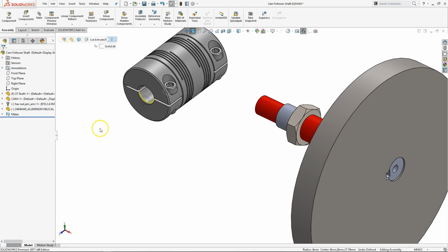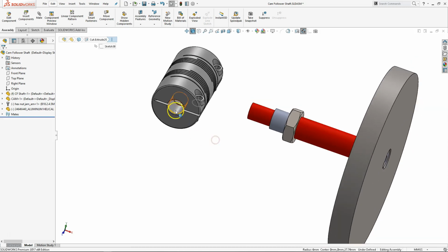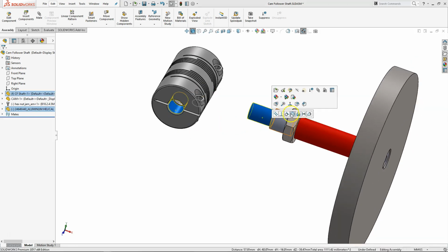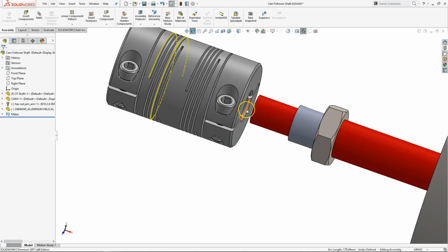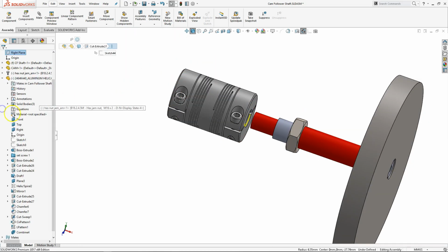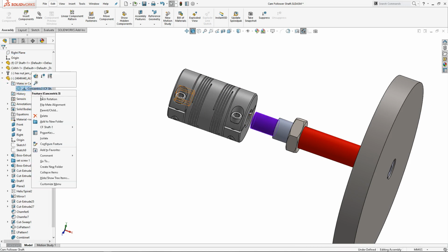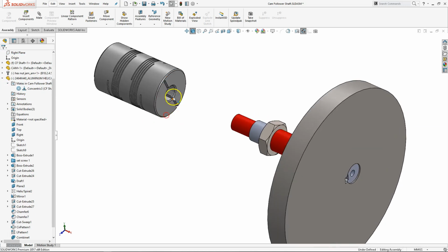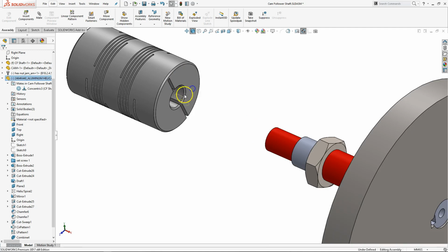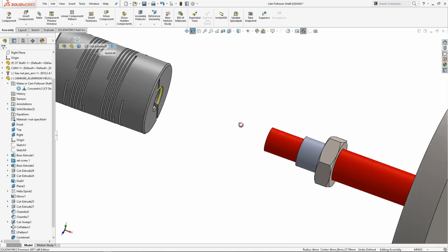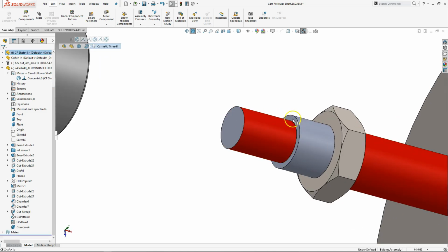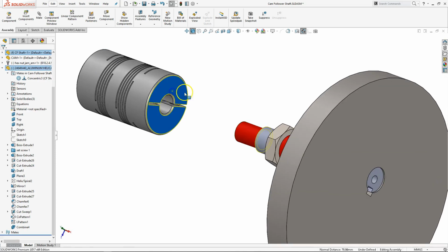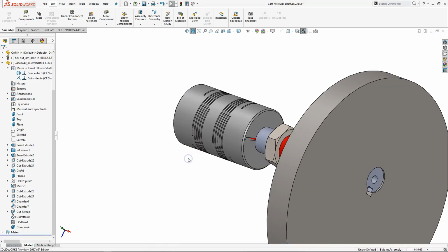Okay, so on the diameter we have the radius of 6. Go ahead and make that concentric and pull it back just a little bit since it may have twisted. So that's the 6.35. So what that tells me, I need to go identify the mate, and we'll flip the mate alignment. And then don't really care about that circle. So 6 millimeters on the radius, and then we'll bring that up to couple. All right, so it goes to coincident.